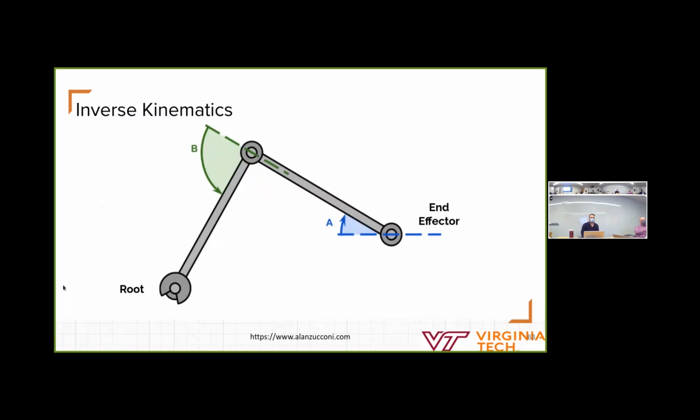As a refresher, inverse kinematics is the inverse of forward kinematics. You have what's called a kinematic chain, which consists of a series of linkages and joints. If you know the position of the first joint, which we'll call the root, and the length and rotation of all the linkages and joints, you can forward propagate to calculate where the last joint, what we call the end effector, is.